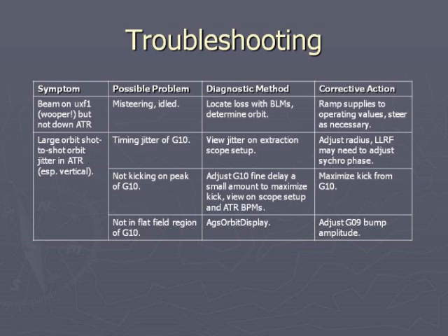I have one question. Where is the threshold measured at physically? I forget where that is. That uses the unnormalized current transformer signal. The time in the cycle we measure it at, we have some control over, so you want to measure as late in the cycle as possible to be sure that you still have beam as late as possible. But there's a certain amount of time it takes to inhibit, so I don't know how close you can get to the actual CFD request before the inhibit won't get there in time. You said the trigger is adjustable. The time at which we measure and compare to the threshold is tunable. We typically don't, there's really no reason to. We put it as close as possible and then just leave it there.